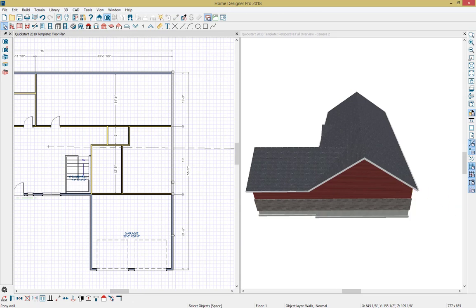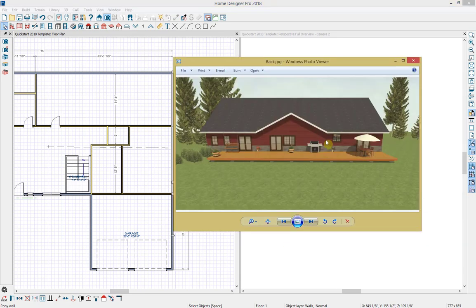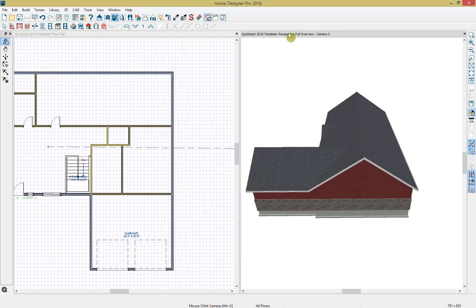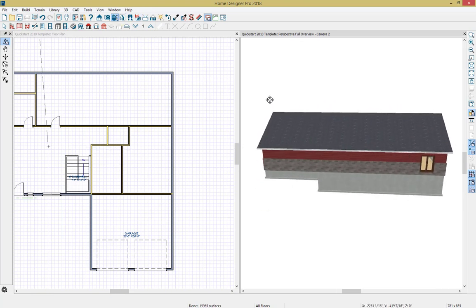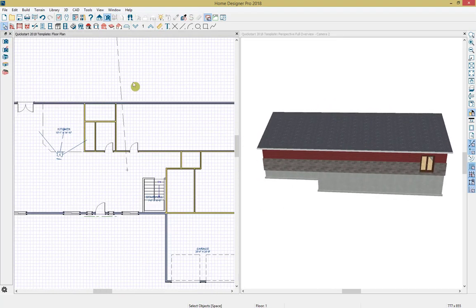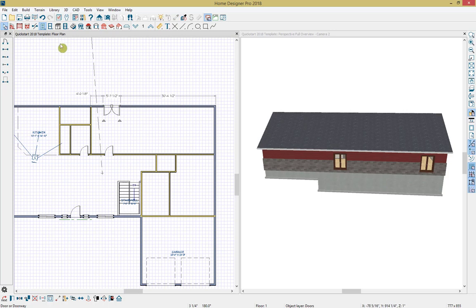And then lastly, if we look at our photo of the back of the design, we have a gable wall and roof in this area right here. So let's go ahead and design this, minimizing that photo, and let's take our 3D view to the back, and we're just going to navigate our floor plan over there. And then let's go ahead and add a few doors while we're at it. So we're going to go up to our door tool and add an exterior door there. And actually, let's place a copy of these French doors right here. So I'm going to press spacebar, select the door, and delete it. And then I'm going to grab our French doors, press copy, and then just place a copy right here. And then add a few more windows into our design. So I'm going to go up to our window tool and then just click and place some windows right there.